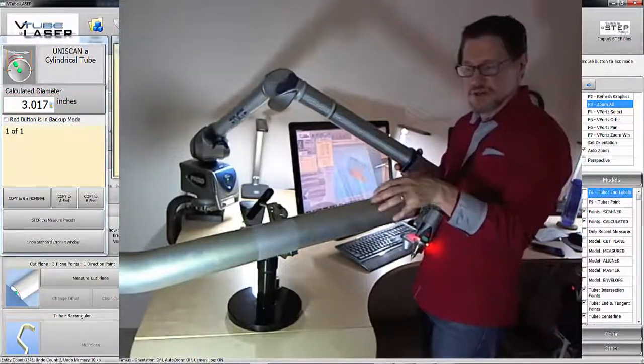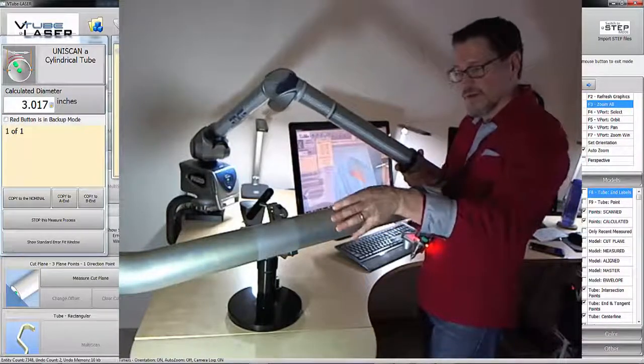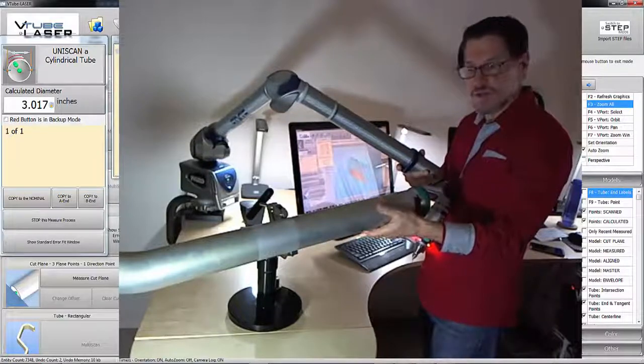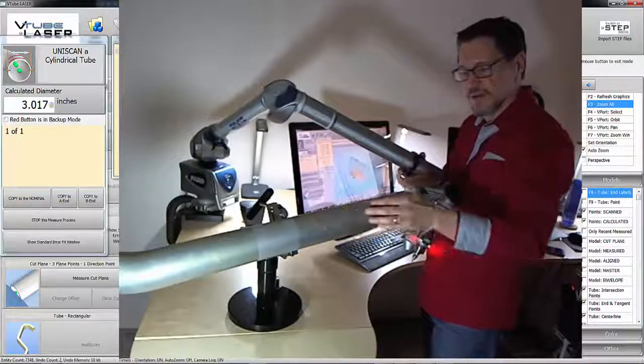So what we see happens when we take a wide diameter scan is we get a more true representation of what's really happening in the straight. It takes into account the ovality and deformation, even in a part that's very precise like this one. So it's important to use as much as possible the wide diameter scan.